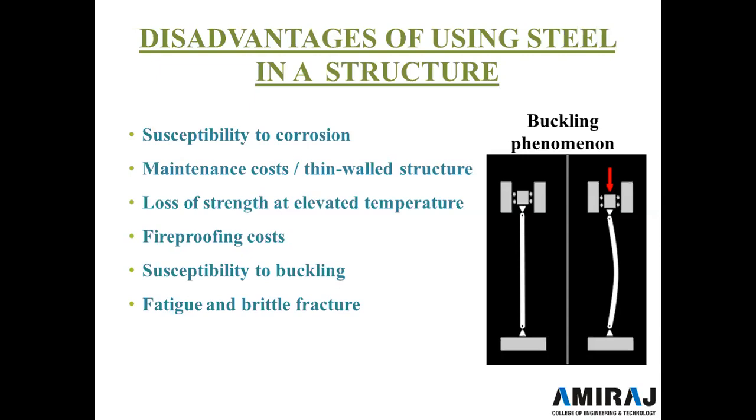In steel buildings, cladding and dividing walls are made up of masonry and other materials. That is the main disadvantage of this structural steel, right? Welding and tightening of high strength friction grip bolts, which is known as HSFG, require proper drilling. In many cases, the cost of steel structures works out to be more than concrete structures, because steel costs more than concrete, right?